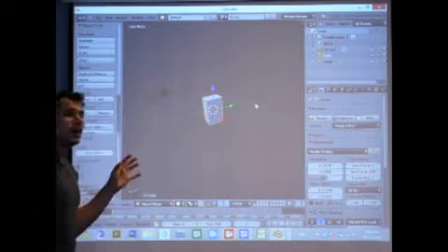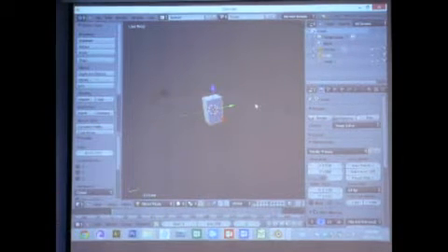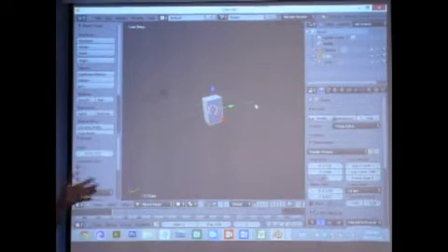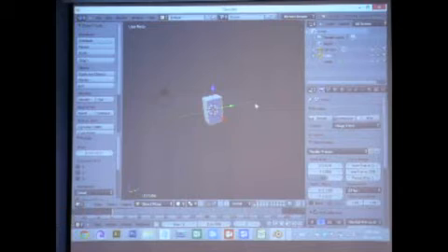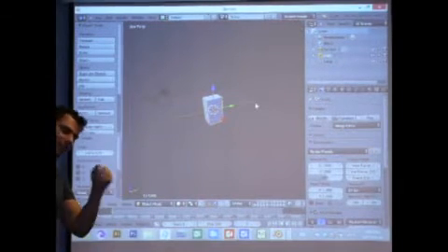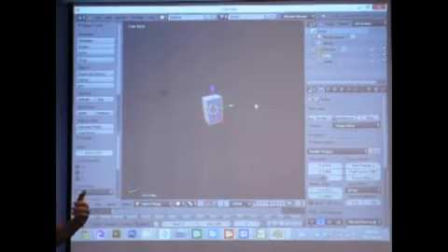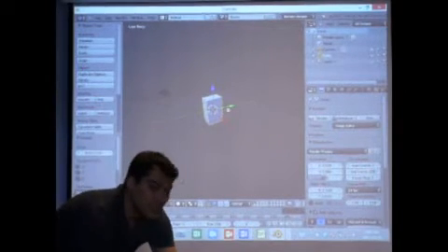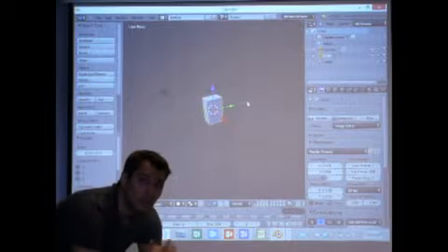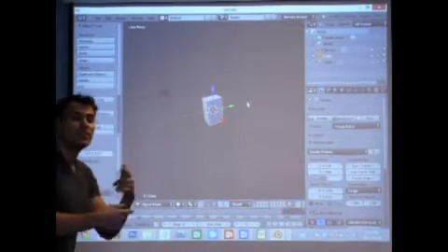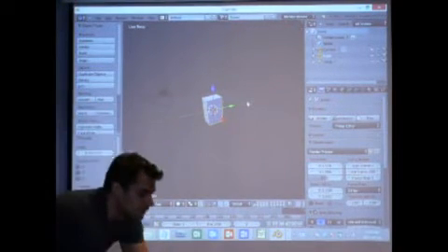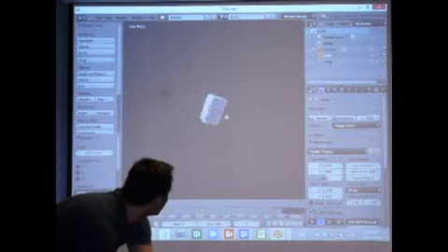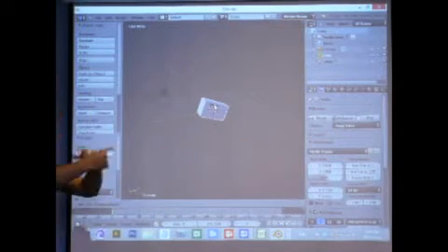So it's just a general rotation, and you can save it. And just in case you want to go back, Control Z, like in every other program. If you messed up something, you didn't want to rotate it that way, or scale it, Control Z, you can go back. Control Y will redo, like most programs. And just like in scale, you can press RX, RY, RZ. So this is very important for rotating things in one dimension. If you press RX, it shows you the x-axis, and it rotates it along the x-axis.